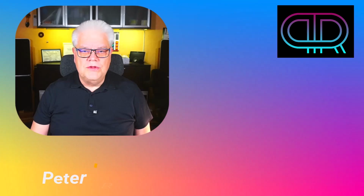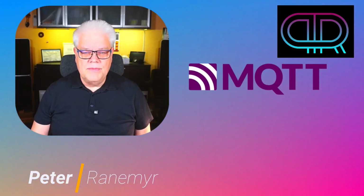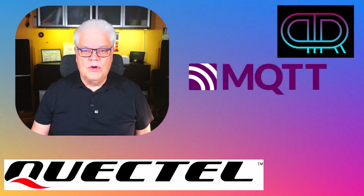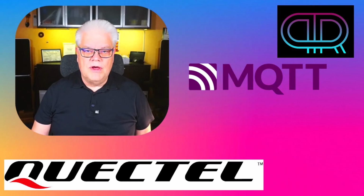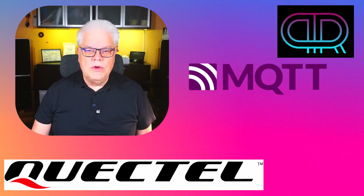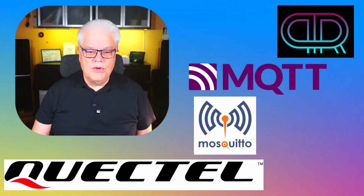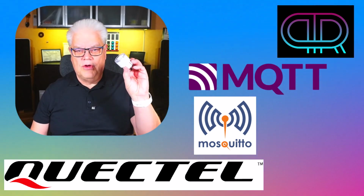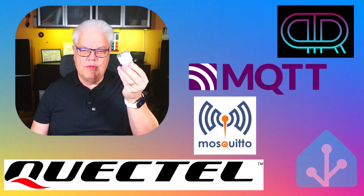Today I thought that we should take a look into MQTT, continuing from the last video where we put a Wi-Fi module on a microcontroller. I have now changed the microcontroller to the STM32 U545 and the Nucleo board there. So what we are going to do is send a Wi-Fi message over MQTT to a broker. And then the MQTT broker will send the on-off command to this sort of connector.